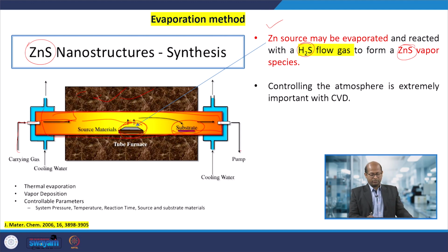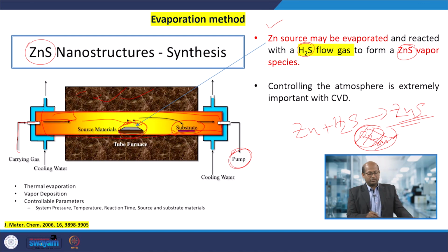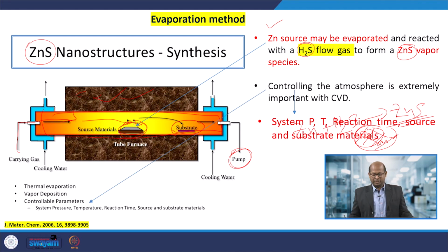Okay. So here a vacuum pump is there also, before that, to eliminate any contamination during these reactions, meaning zinc plus H2S to zinc sulphide, so that would form. If any oxygen or other contamination is there, then pure zinc sulphide will not be obtained; zinc oxide or other things might be possible. So to eliminate any contamination, we have to use some vacuum pumps to have a vacuum in the system before charging or passing or heating up that zinc. Okay, so this way we can prepare this particular metal sulfide by using these evaporation methods.